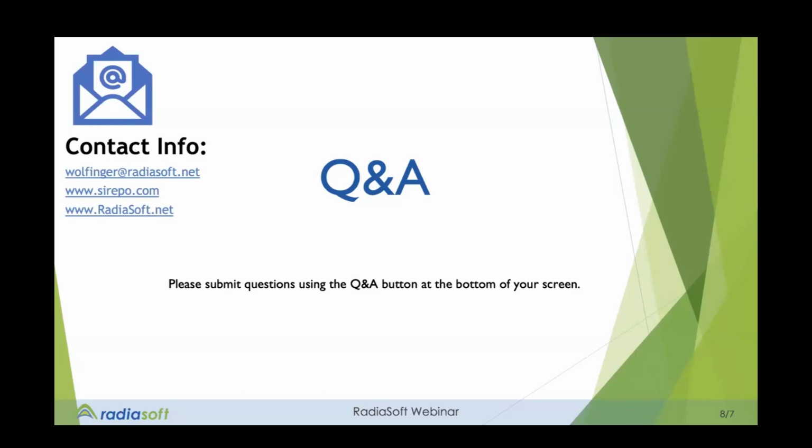Thank you. Next question up is, you had mentioned support for pump pulses involving different repetition rates. Does that mean you support the full range from 1 Hertz to 1 kilohertz? That's also a good question. This is a little more of a tricky area. So pumping at 1 kilohertz is more of a recent implementation, and it results in the crystal temperature increasing. And so you can reach a steady state at 1 kilohertz, but in between the range of 1 hertz and 1 kilohertz, it's a little less well defined. So we do support some frequencies within that range, but not the full range itself.